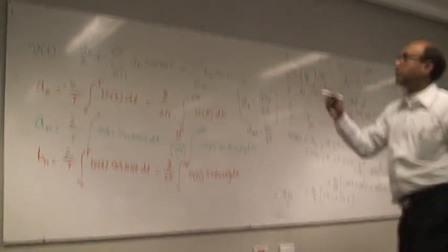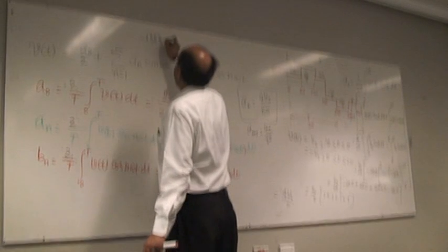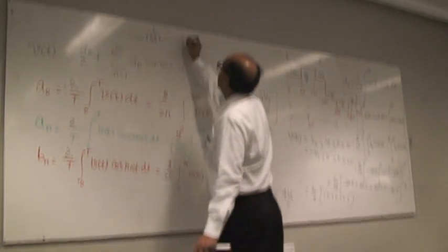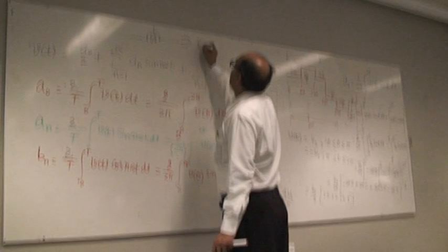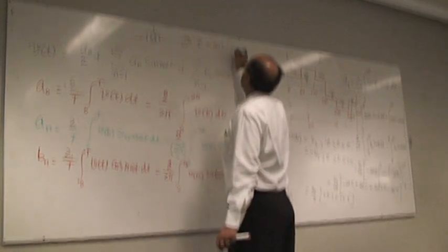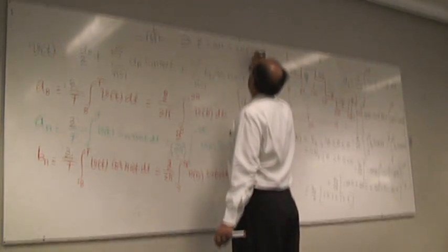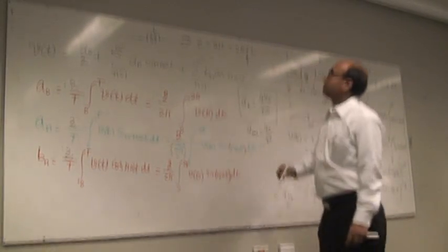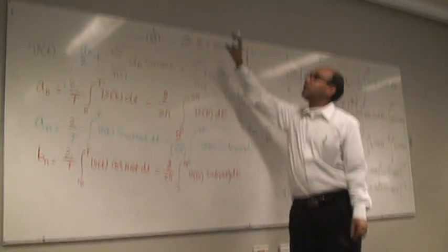Is that why they warn you when you're using a really small value inductor, because it means the harmonics will be more intense? Yeah. If you use really big inductors, you avoid the harmonics problem. If you use small ones, you end up with interference and stuff. So effectively, your L is the value, but impedance-wise it is omega L. This omega is 2 pi F. So if you increase your F, then the impedance value of the same small inductance can be large.